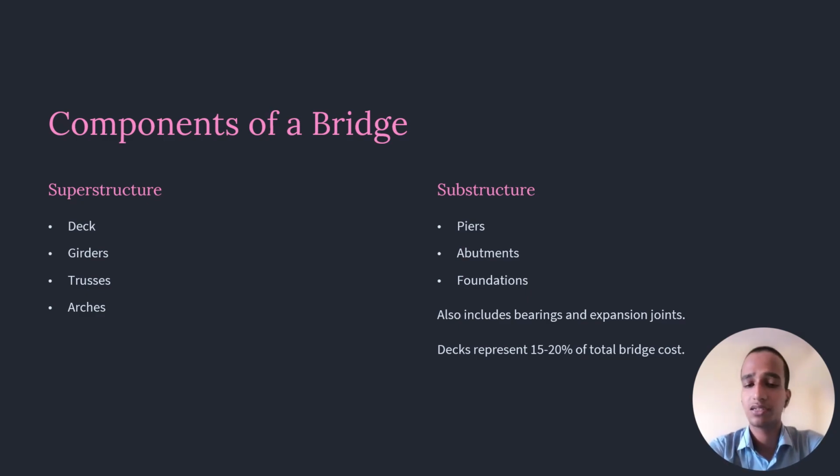Second is the substructure. In the substructure part, there are the piers. Piers are the foundation part. Second are the abutments. The abutments are below the surface of the soil, subsurface. And third is the foundation. The foundation may be a deep foundation or a shallow foundation.